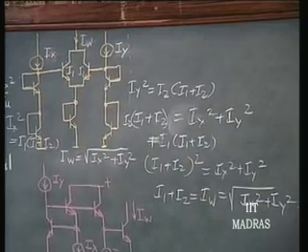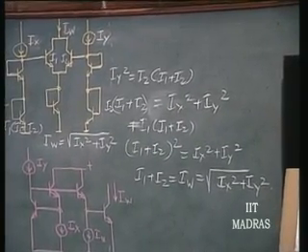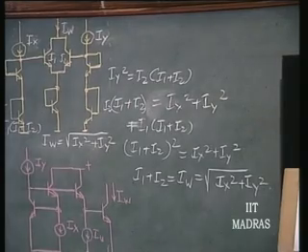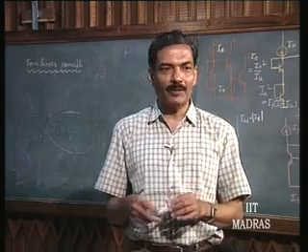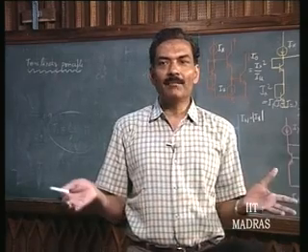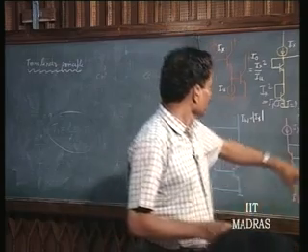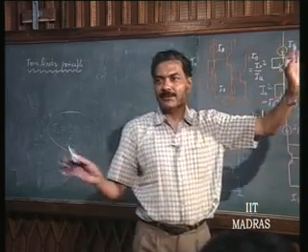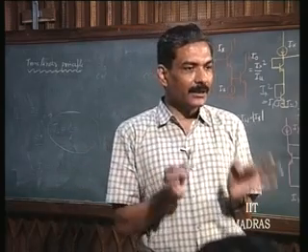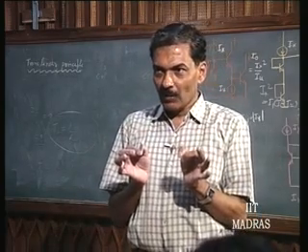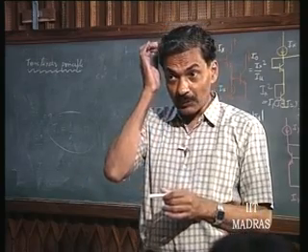This is an important circuit. Ix and Iy are the two inputs, and output will be a current which is root of Ix squared plus Iy squared. What is it? Vector magnitude. So, this is a very neat circuit. You can see just using transistors and diodes I am able to obtain a very complicated signal processing formula, which is nothing but vector magnitude, root of Ix squared plus Iy squared.